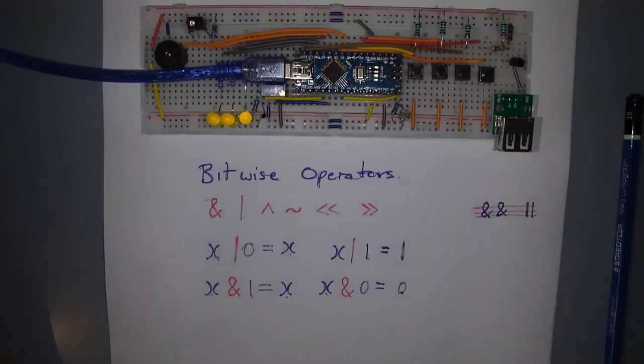So as I said, this is an extra, and it won't at all be assessed, because now what we're looking at is we're looking at the machine code to see what this line of code actually turns into when it's assembled. And so what happens is that these numbers 95B1, 917F, 95B9 are written into the flash of the microcontroller. Remember, it's this machine code which is written into it. This C code is compiled into machine code.